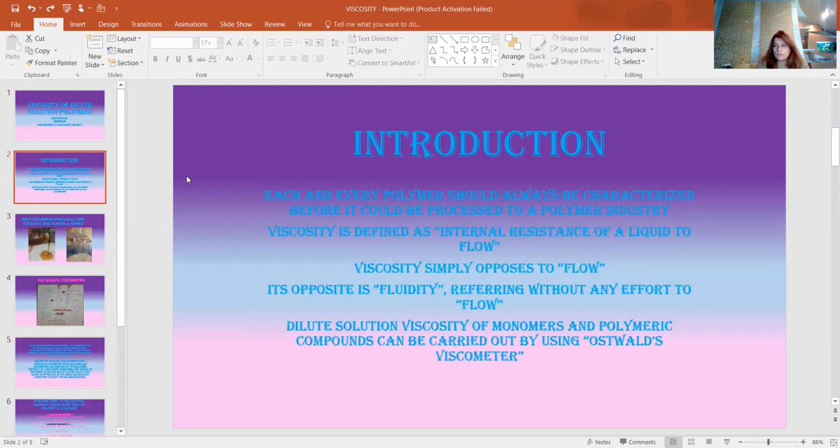and then it is ready to use to compute your viscosity. You will fill water inside it, because you need to calibrate your instrument before you carry out the other measurements. So you need to calibrate the viscometer first. I will explain to you in my next video how you are going to calibrate your viscometer.